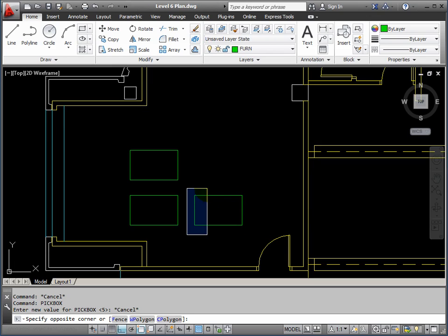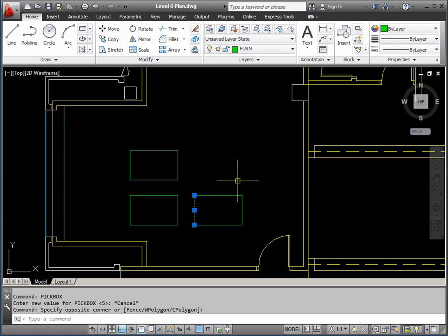Okay, now if I select here, I would end up with only one line selected, the full line that's inside that shape. It wouldn't pick any others because it's quite weak. See what happened? So the second pick, it only showed me the one. Now press escape and try that from the other side.